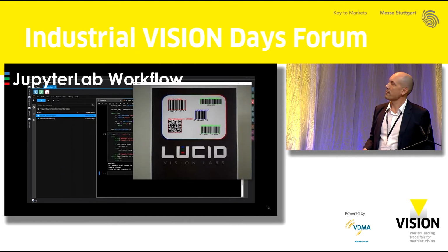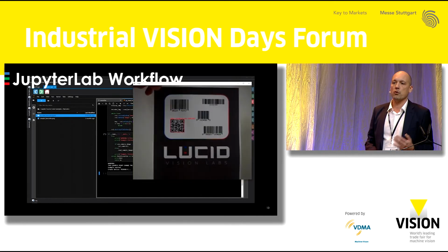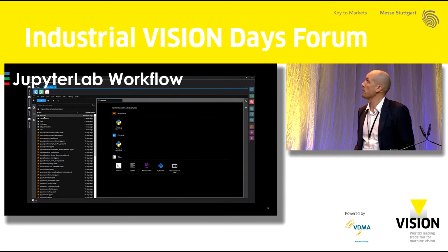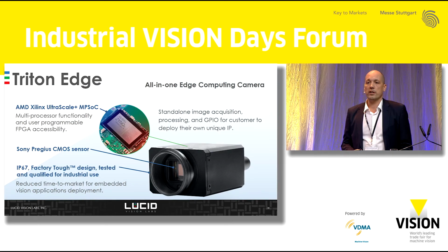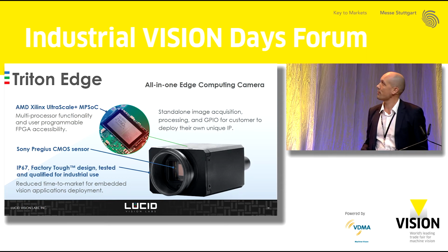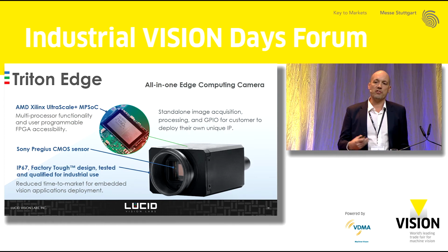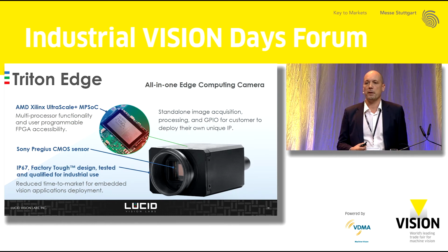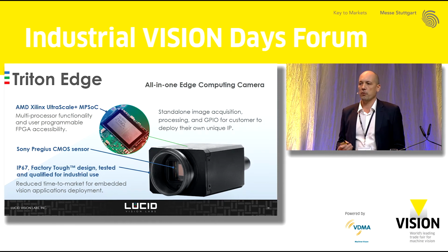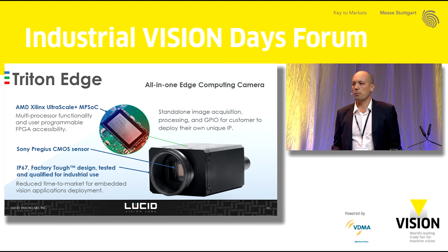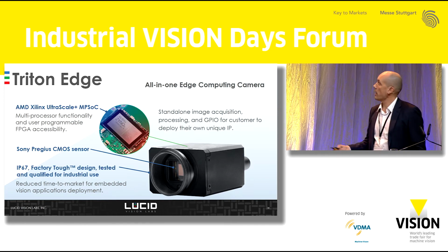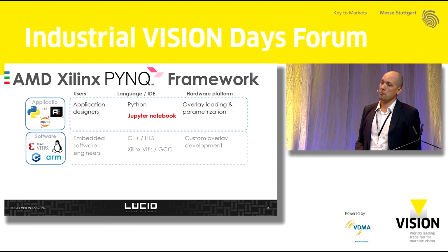That's on the, let's say, standard system side. We know also there's a demand to go more to the edge and provide edge analytics capability. Lucid has been working on this product, the Triton Edge camera, which looks like a standard GigE Vision camera, but is actually an edge analytic device that includes all the standalone acquisition, processing, and machine control through the GPIO with a Xilinx chip. So it's an AMD Xilinx multiprocessor SoC that includes both FPGA fabric, hardware logic, and a general purpose ARM CPU that can be accessed and programmed using the Xilinx PYNQ framework.